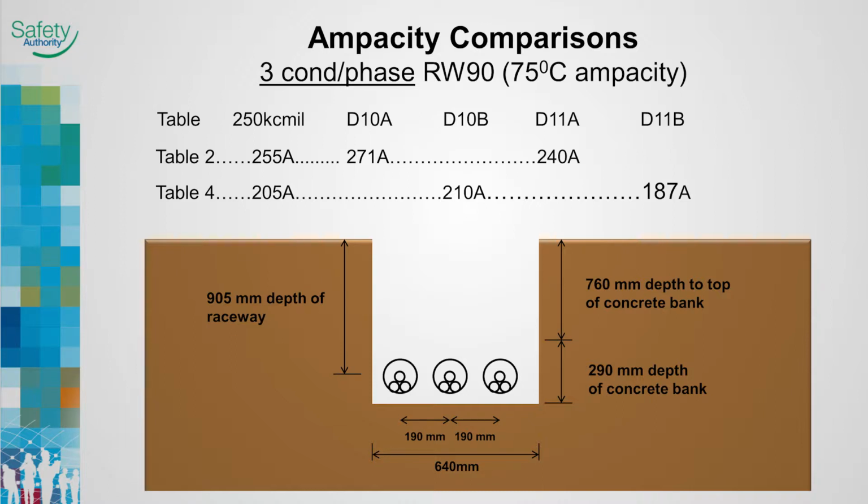If 3 times 187 amps was acceptable for the load requirements, then no transition conductor is required, since the above ground conductor portion of this installation is sized and has an ampacity complying with Rule 4-006.